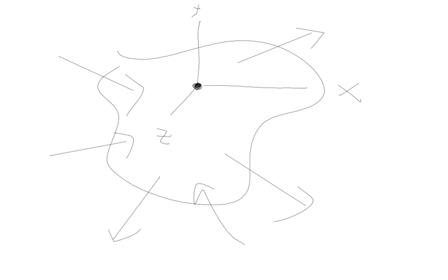And things are just much easier to work with, okay? So with all of that in mind, when we look at the stress at a single point, what we need to do is come up with a way to visualize that point such that our stresses are always just in our coordinate directions, x, y, and z, okay? And the best way to do that is to represent a point on an object as a cube.